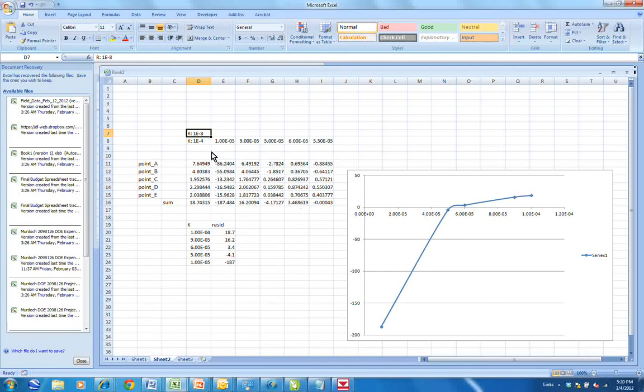So 5 or 6 tries to get our value of K, and then if we do something similar where we iterate and adjust values of R, we should be able to do this 3 or 4 times and come up with a calibrated model. So give that a try and see if you can estimate values of R and K that best fit the data.